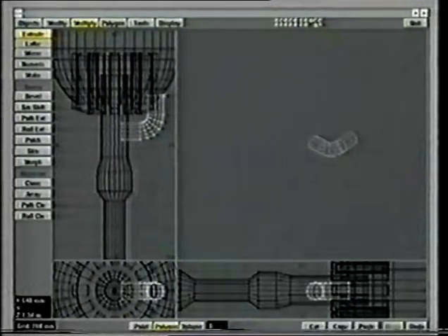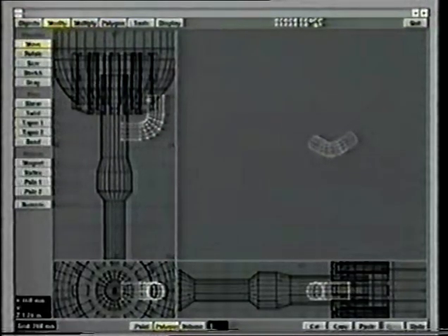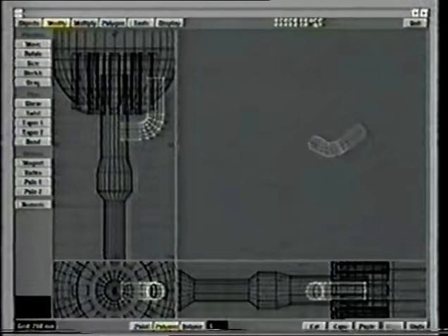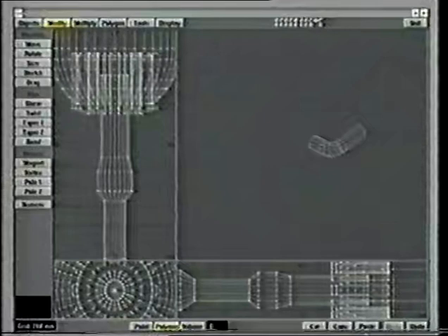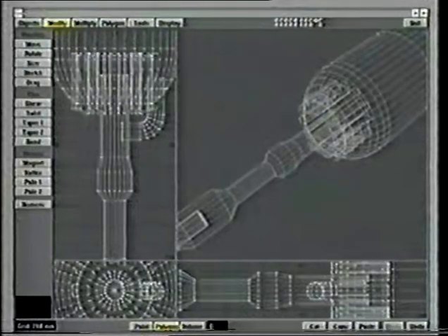It's not quite getting into the surface of this here. You can see that there's a small gap just on the edge. So what I'm going to do is just select that polygon there, modify move, and again using control to constrain it to one axis only. Okay, that's there. So let's have a test and see what this looks like by pasting it into the other layer.